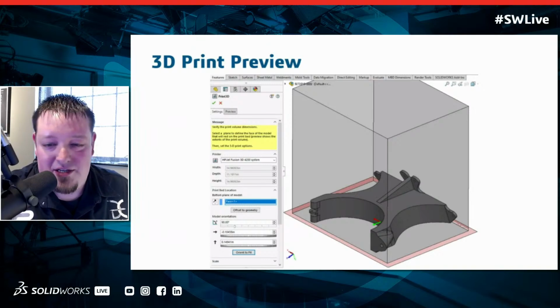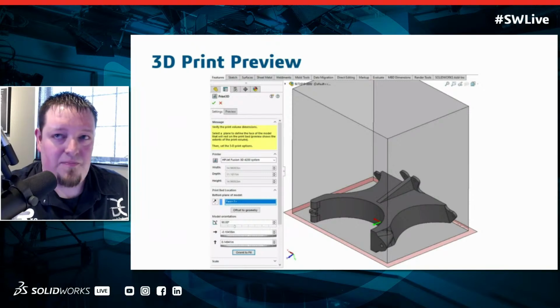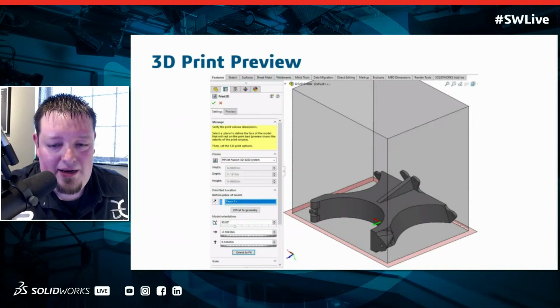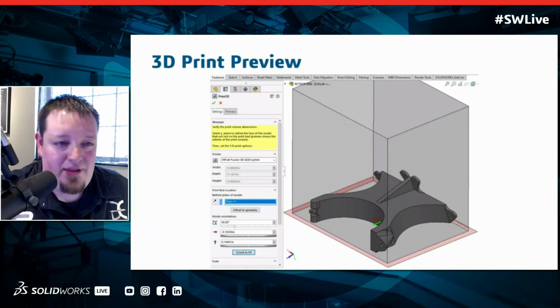You can go in here and actually find the HP Jet Fusion 4200 and see, does my part fit, or am I going to need to put glue joints in? Am I going to need to plan on orienting it differently? So this is a really handy tool, just so that if you know what type of printer you're going to be running your parts on, and reach out to your additive manufacturing partner. I have customers reach out to me all the time. I go, oh, we're going to run it on this, we're going to run it on that, and then that way they can come back in here and kind of see how their parts are going to build.